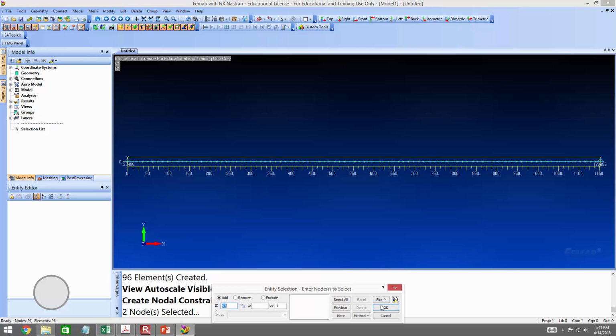And now it looks a little different since we're looking in the nodal perspective. The last time when we were applying boundary conditions to the geometry, that little F popped up. It said fixed. Since we're looking in the nodal point of view, see how it says 1, 2, 3, 4, 5, 6? That just means it's all three translations and all three rotations. Now, we've got pinned boundary conditions to apply. Here's where this work plane comes into play. Where did we say? Here, here, and here, right? Now, how do you determine where 288 is, 576 is, and what have you? The work plane.